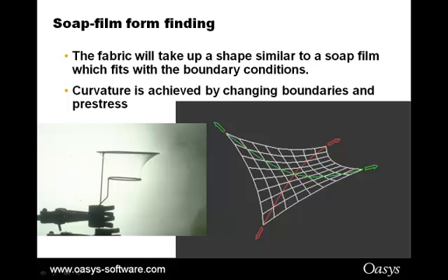And you can think of the 1D elements as having constant tension and 0 stiffness, a bit like some elastic band type things. Note that you will have to keep control of the structure when they're exhibiting 0 stiffness, and we have to use spacers for this. I'll come back to those in a moment.